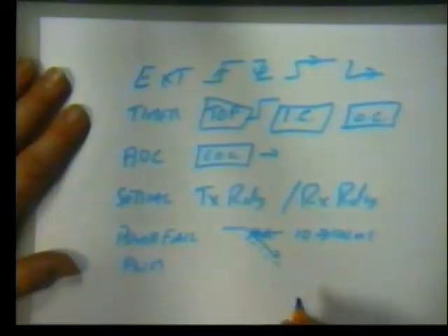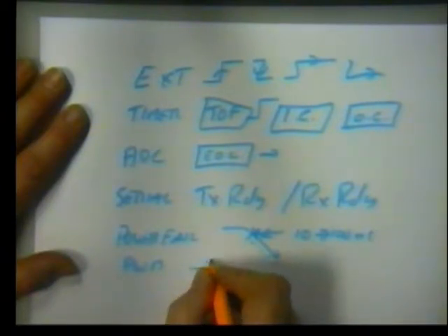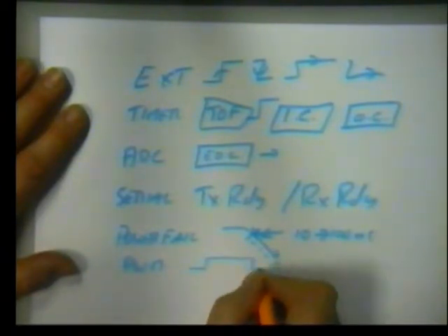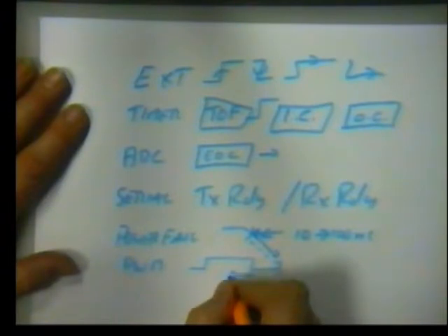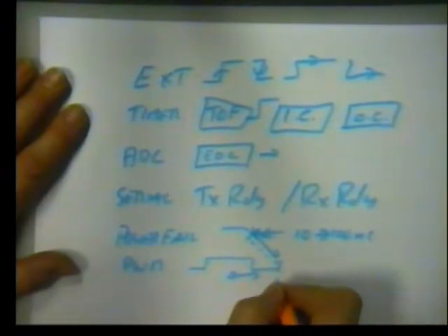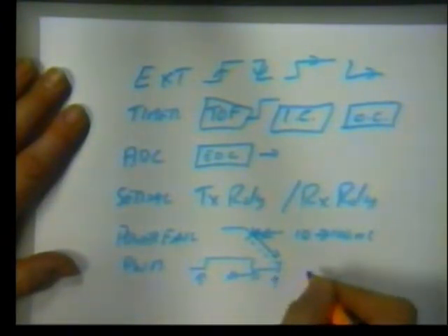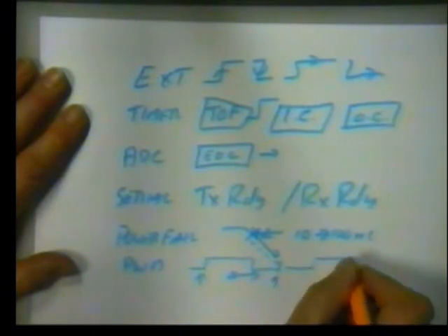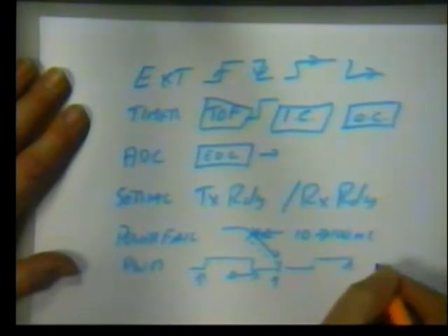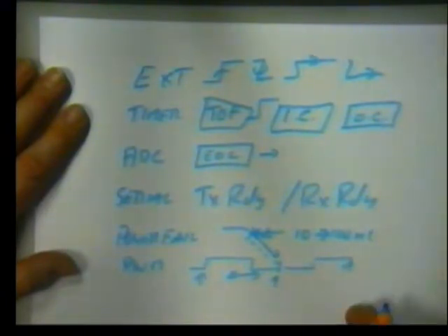Pulse width modulation, watchdogs. You can get PWM interrupts. Remember, PWM is this concept whereby we have a variable mark-space in a fixed frequency. So it's sometimes useful at the end of each of these periods to have an interrupt in case we want to reload a new PWM period.